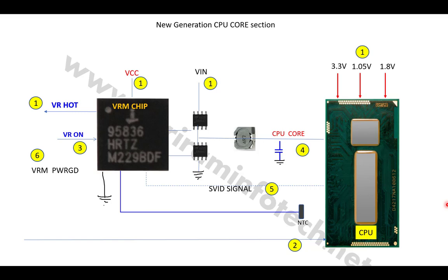Okay. So the CPU core voltage is the final voltage for the CPU, and before the CPU core voltage, a number of voltages are generated, like 5 volt, 3 volt, 1.8, 1.2, 1 volt, 2.5, and 0.6. There are a number of voltages generated, and all these voltages go to the related components like the PCH or the bias. Here the CPU and the PCH are combined, but still those PCH voltages go to this chip.